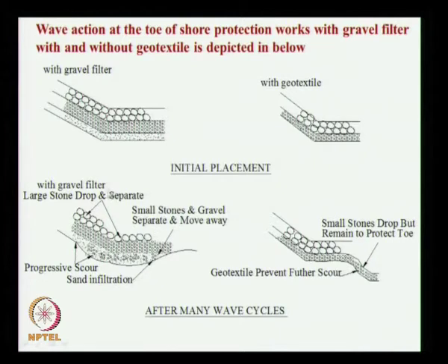This is the disadvantage, and over a period of time you see we have 2 layers of stone, some of the stones are not here, missing, it might have been taken away by the waves or it would have gone inside. So here we have the geotextile filter, it does not allow the seabed material to go inside, this does not allow this cover to take place.